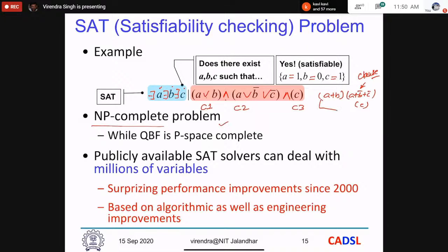But fortunately, when the clause set is satisfiable, in reasonable time we can get one of the solutions, because there can be multiple solutions. For example, that's what I said: if it is an AND gate and the output is 0, then there are multiple solutions, and one solution I can hit quickly and then it can solve.